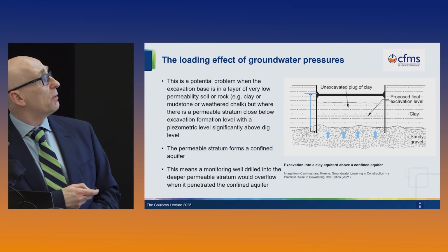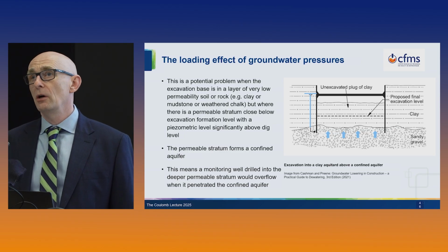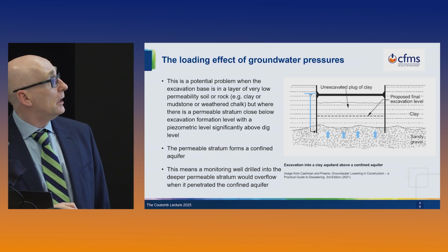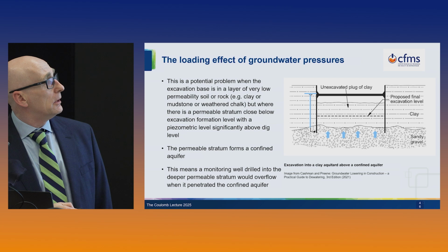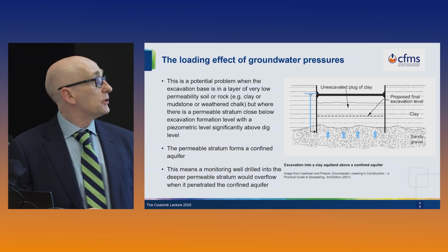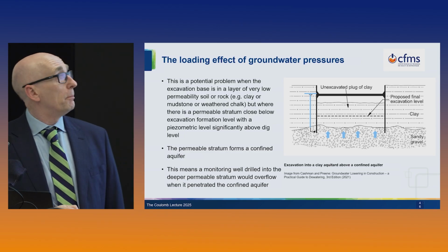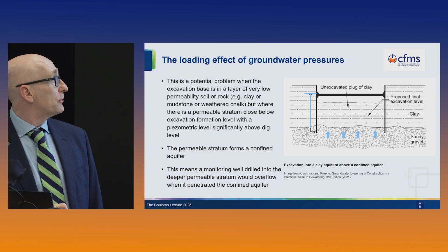So this occurs where we're excavating down in a low permeable material. It might be a clay, a mudstone, it might be structureless weathered chalk. But at some depth below us, there is a permeable stratum, and importantly, it has a piezometric level that goes above excavation level. So essentially, we have what we call a confined aquifer here, and then we're going to excavate down without reaching the aquifer, but we're going below the piezometric level.